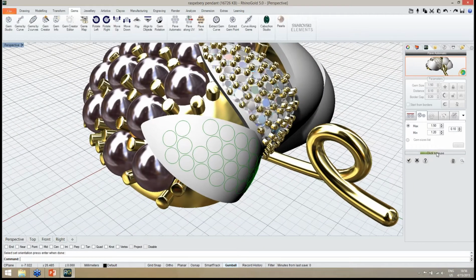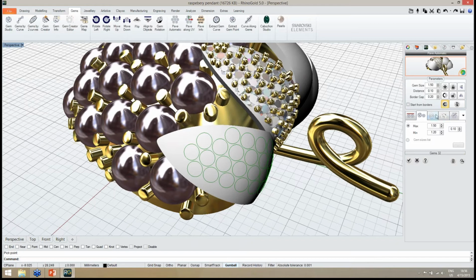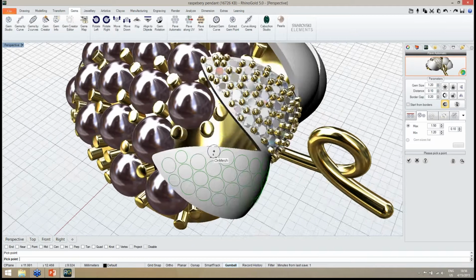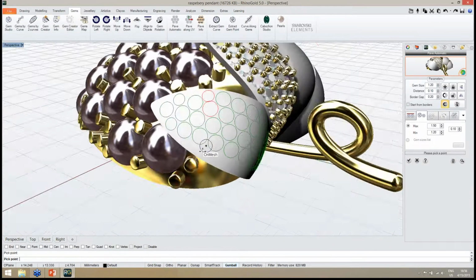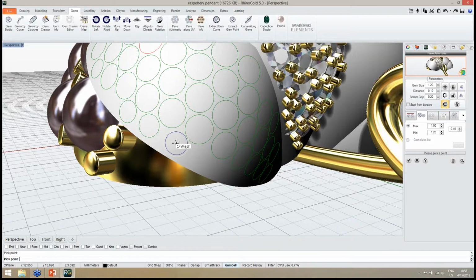For instance in here I can pause and I can add manually a gem just to make sure it will add 1.5 in here, and I can start again, recalculate, try to add more, or I can manually adjust the position. Maybe let's see if 1.5 it's good for here, then probably I can use 1.2, 1.2. I'm not sure if this is enough. Then I can reduce the others to make sure it will fit correctly here.